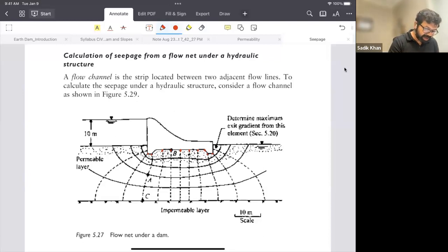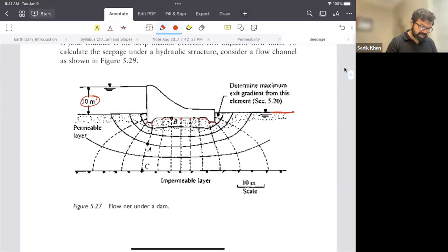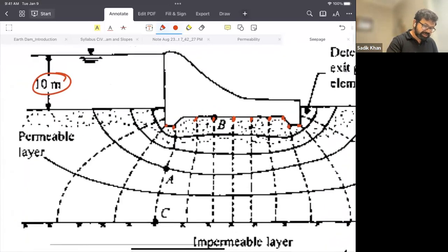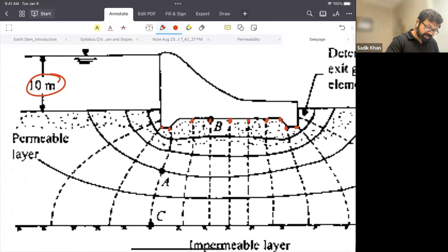So basically, we have H equal to 10 meter, and the other point is given. But in this type of problem, it's always better to find the elevation. Remember it: always convert to elevation instead of height, because there is always an elevation difference, and if you have an elevation difference, your pressure changes. So in this diagram you have some difference in your height. We need to check if these are the same lines. Yes, it does.